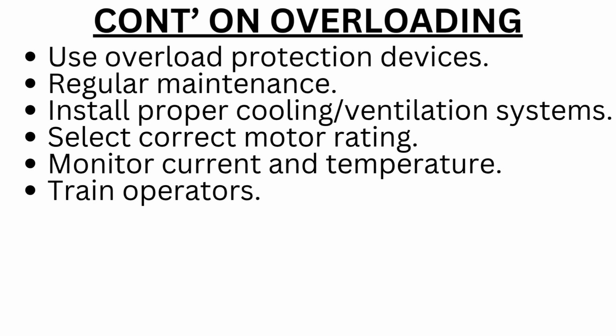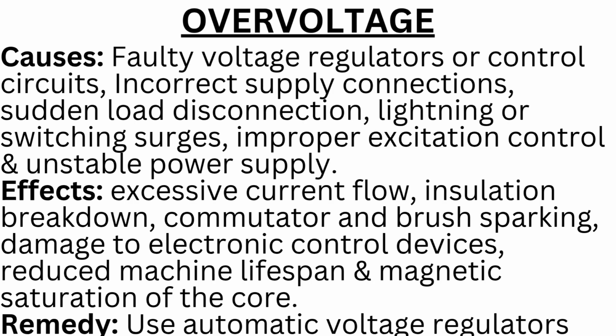Use overload protection devices. Regular maintenance. Install proper cooling, ventilation systems. Select correct motor rating. Monitor current and temperature. Train operators. The next operational failure that we will look at is overvoltage.